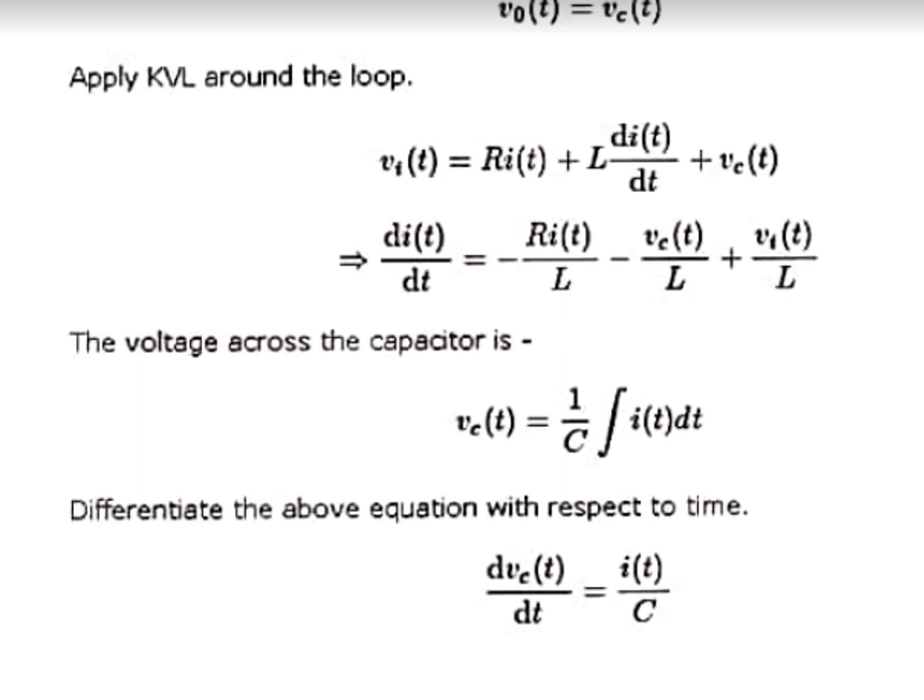Here I of t is one state variable, Vc of t is the other state variable, and Vi of t is the input. Consider this as one equation. Similarly, the voltage across the capacitor, Vc of t, is equal to, we know the formula, 1 by C into the integral of I of t dt.